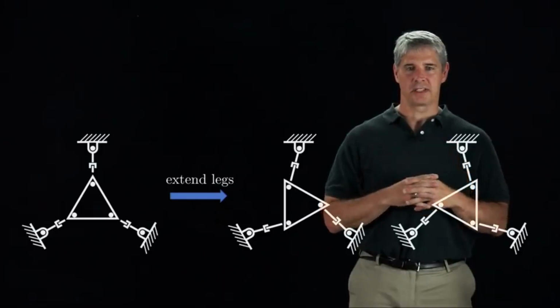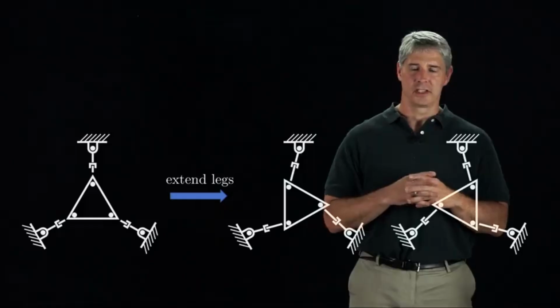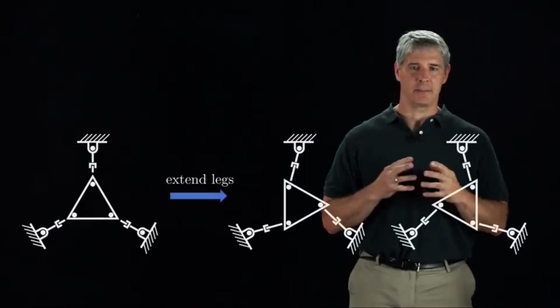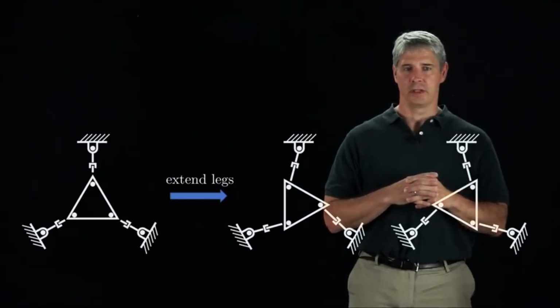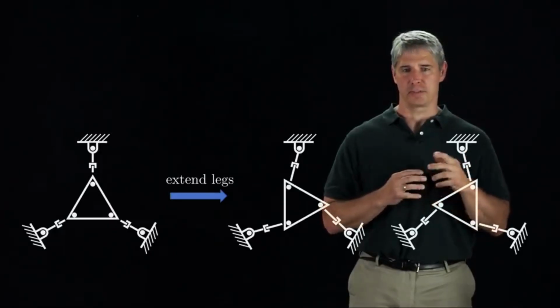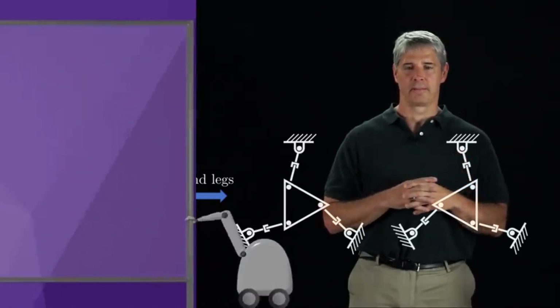Closed chains can be subject to several types of singularities described in detail in the book, some of which have no analogs in open chain robots. Examples include configuration space singularities, actuator singularities, and end-effector singularities. Some of these singularities occur at configurations where the constraint Jacobian, which is the matrix of derivatives of the loop closure equations with respect to the passive and actuated joint variables, loses rank.